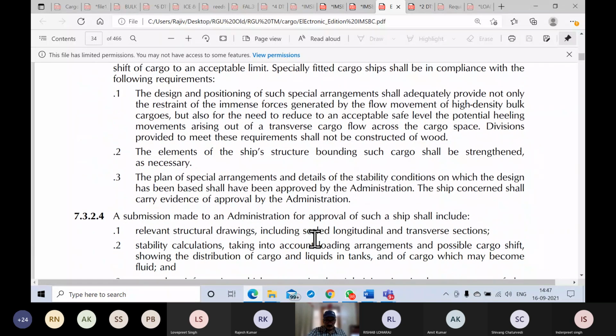But really speaking, the most important thing is that the present moisture content, MC, should be less than the TML. Only then is it acceptable for loading.